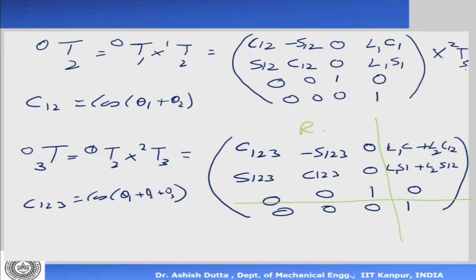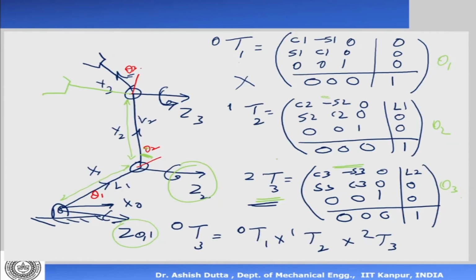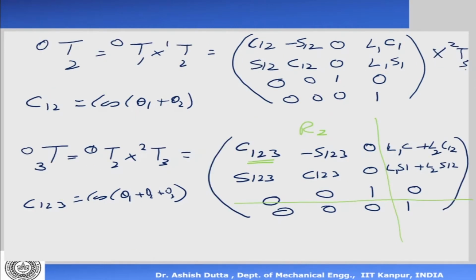Now the rotation set cos minus sin, sin cos, which is a rotation about the z axis, and this is theta 1 plus theta 2 plus theta 3. So the total rotation that this manipulator has had is the sum of theta 1 plus theta 2 plus theta 3, which you can see from here, right? So the total end effector rotation, this is the third frame. The total rotation of that third frame will be the sum of theta 1 plus theta 2 plus theta 3, and that's what we're getting here. And this is the rotation about z. Okay, so it's correct.